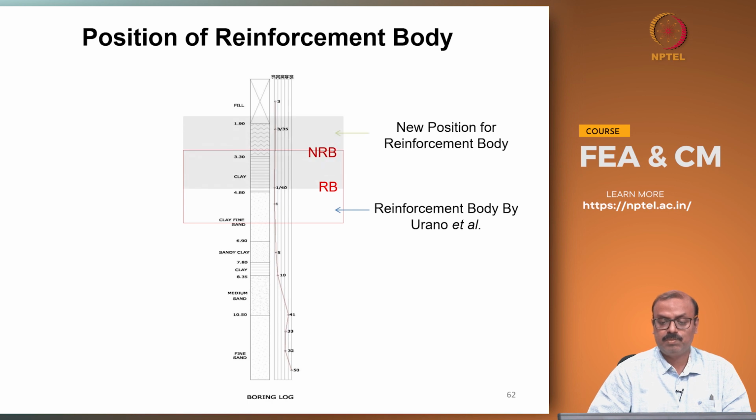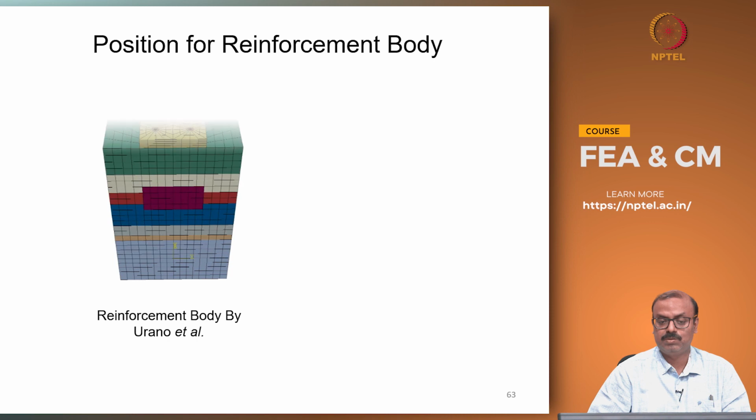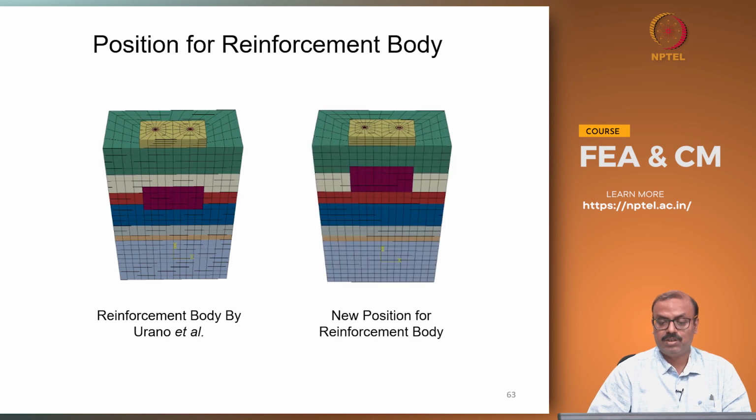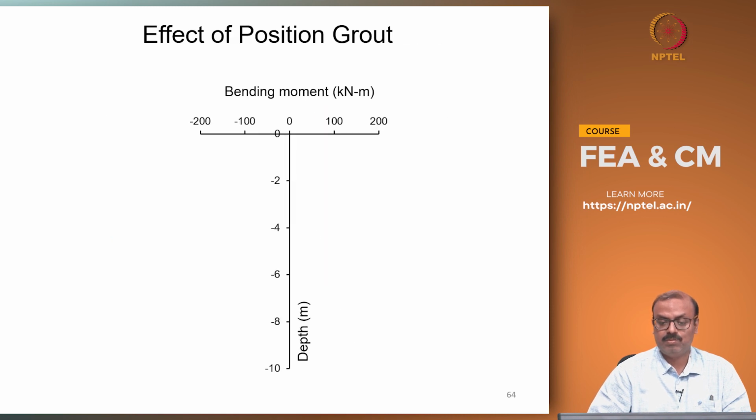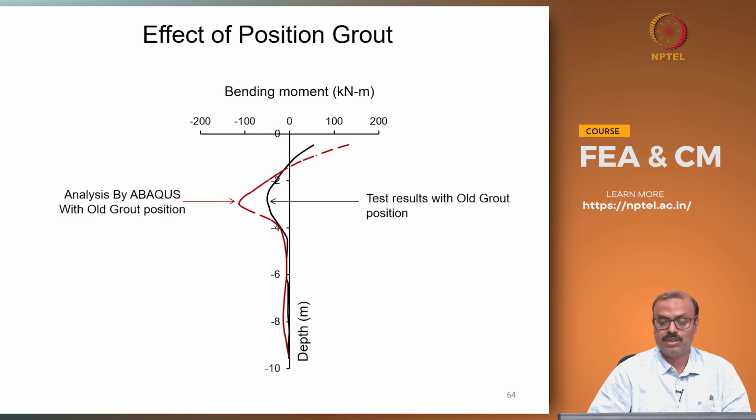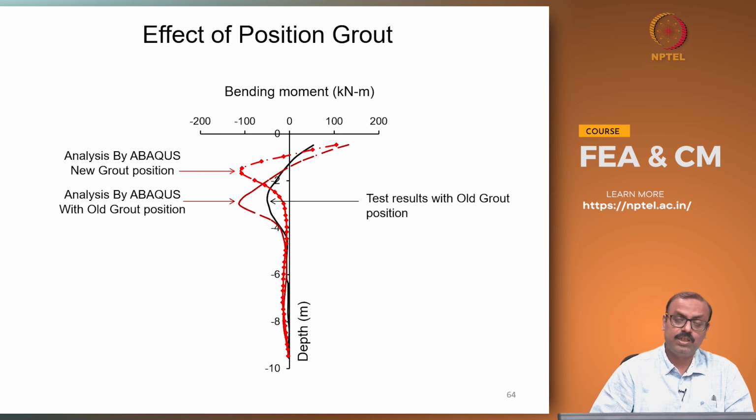We did a bit of parametric study to see if you change the position of the reinforcement body, depending on the soil condition, whether that makes any difference. So, this is the old grout position, this is the analysis by old grout position in Abaqus. There is no change in the bending moment, but there is a change in the location of the maximum moment.